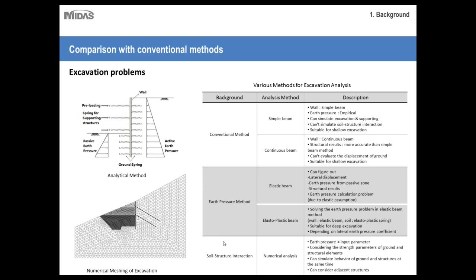So next, let's talk about soil structure interaction, which is specifically done with numerical analysis. For example, if you had a project where soil structure interaction would become especially prevalent, say a high-rise building, a large warehouse, an industrial plant, projects of that nature, then it would become more prevalent because design codes require that you check for soil structure interaction. Essentially, it describes or calculates the behavior of a structural element that's directly in contact with the ground.